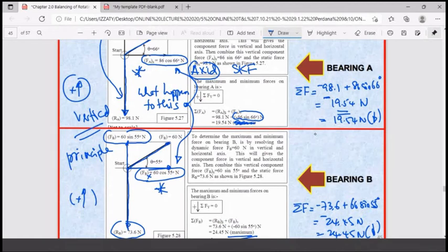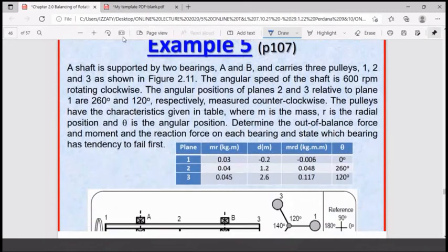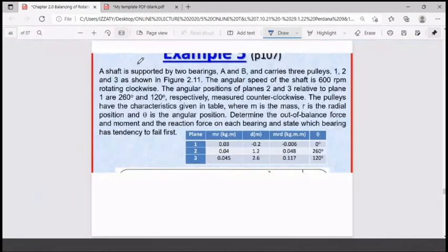So for engineering purposes, when you are designing, if you call the vendor, the vendor will tell you what the principal force is and what the axial force is. Then we check the handbooks. But as an engineer, you know that the axial force is very small, and it will be absorbed by the bearing itself. Okay, so that's about it. I think that covers the topic.